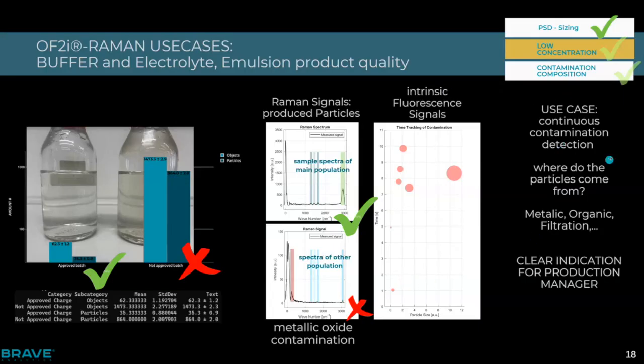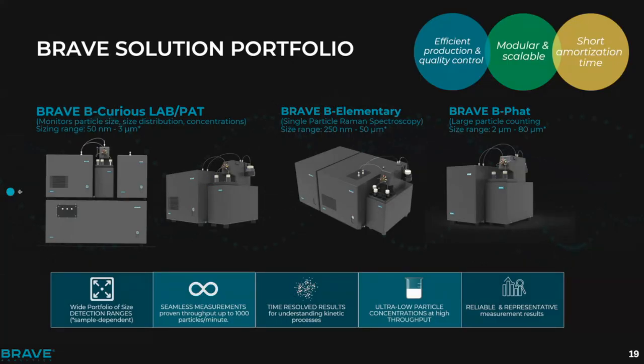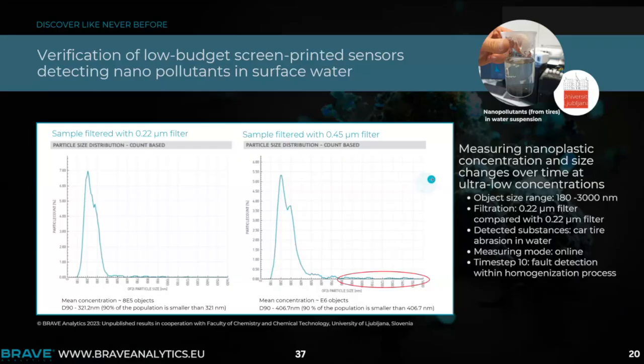So the use case was really to find contaminants at the beginning in a product like pharmaceuticals or biotechnology and so on. It really helps to give production managers indication for predictive maintenance, find faulty materials, and find wear in different tubes and so on. When we then presented our spectrum, having this characterization, going from a size range of roughly 250 nanometers to 50 micrometers for our Raman spectra, we looked, as I said, into different behaviors. So low concentrated particles